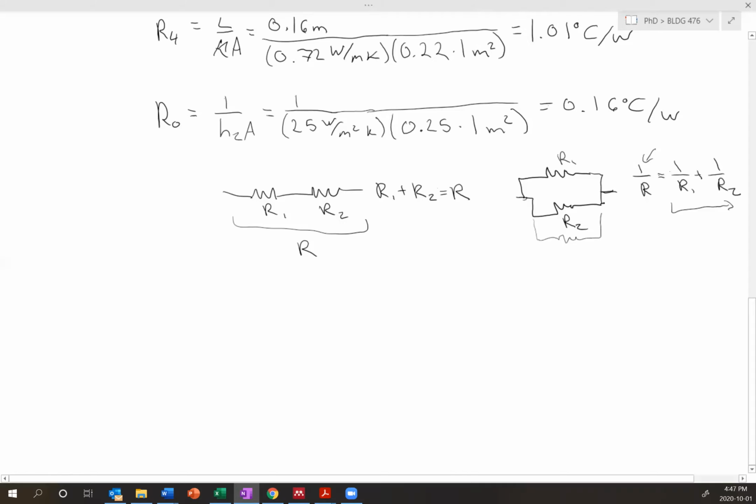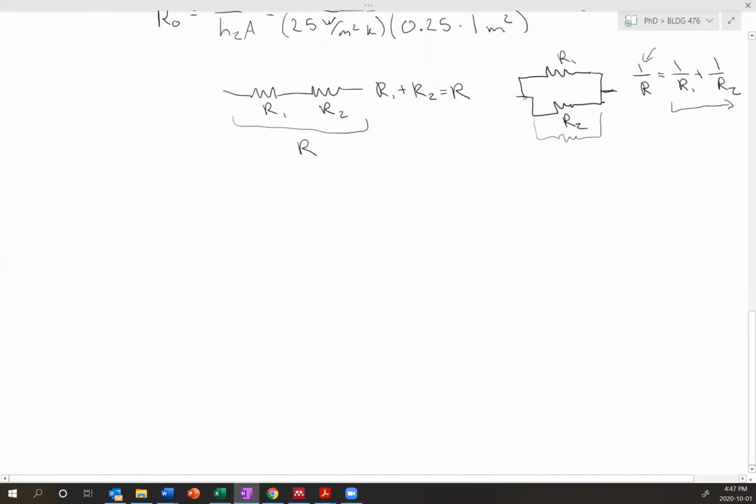But this one is more versatile because we can keep adding on resistors with this format. And so this equation is going to be the one we're using for this because we have 3, though 2 are the same. You could do it with the fancier version of this, but I like this one because it's a little bit more versatile. So our R, we're going to call this mid, and what we mean by that is the brick plaster cross section that had the 3 resistors.